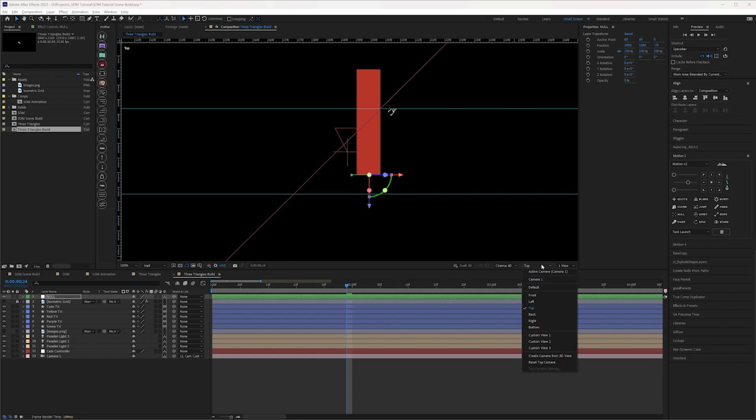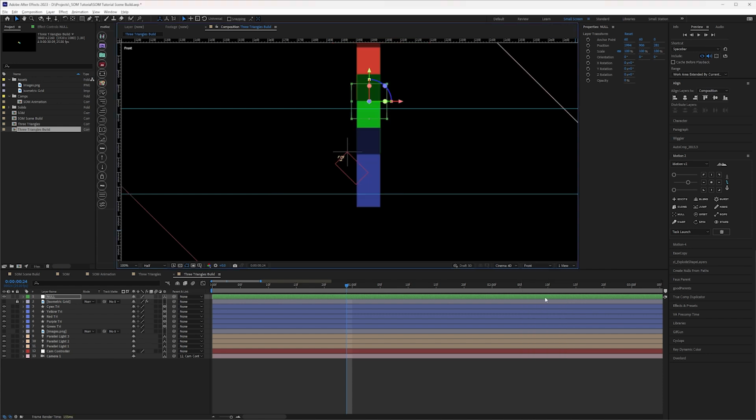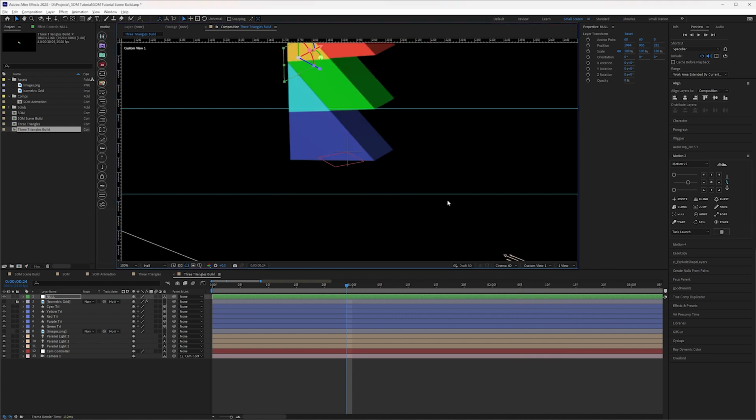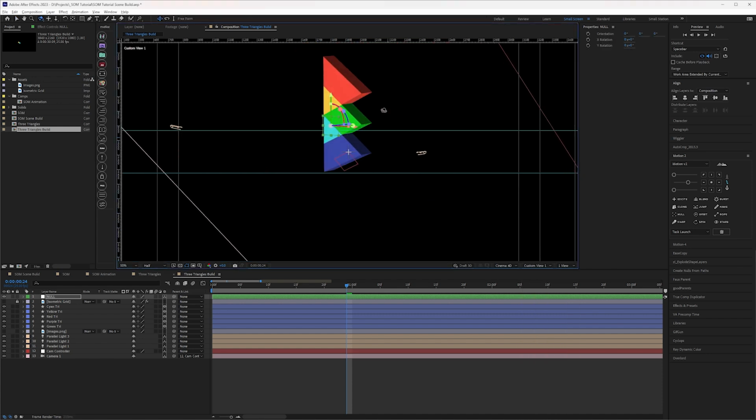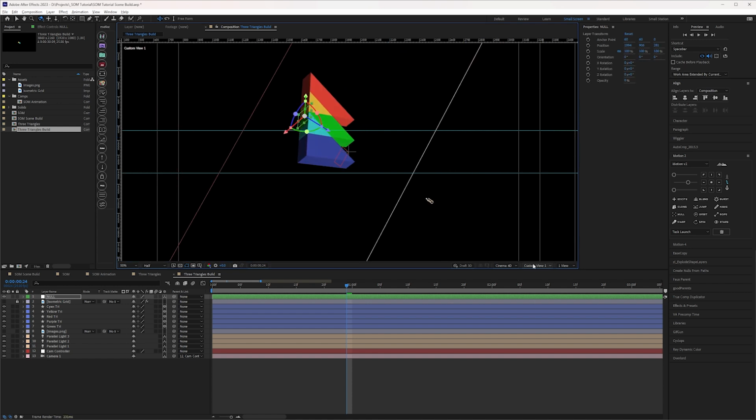Since we are looking from the top, if we are looking from the right, we need to be on top of our triangle here and push it all the way to the bottom. Let's double check from front view, from custom view as well. Let's rotate the camera and make sure we are exactly at the base of our triangle here. Yeah, I think we are good.